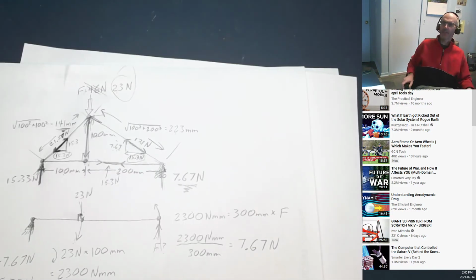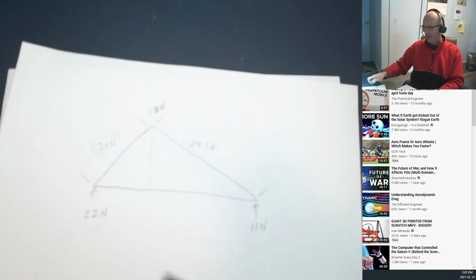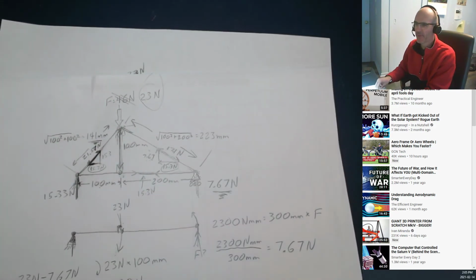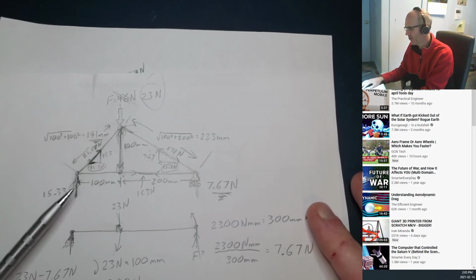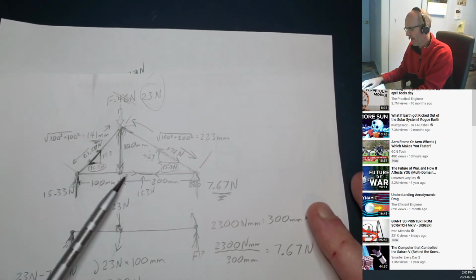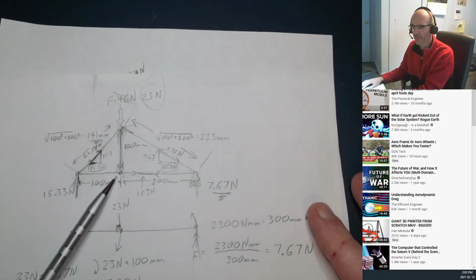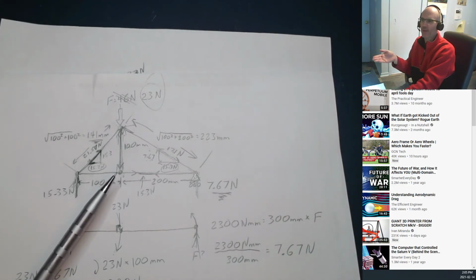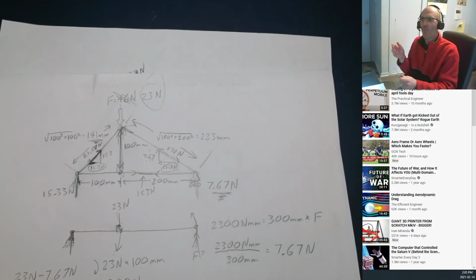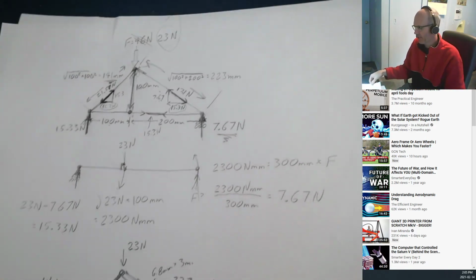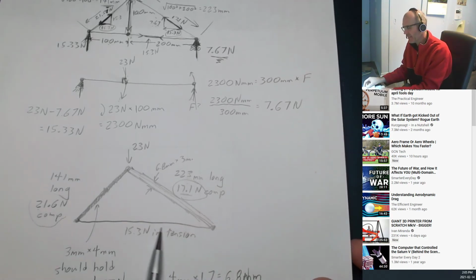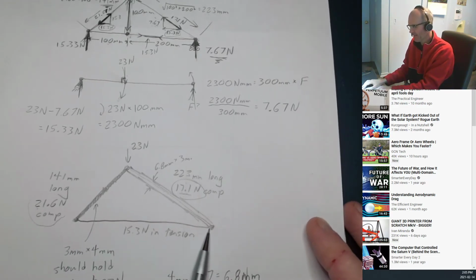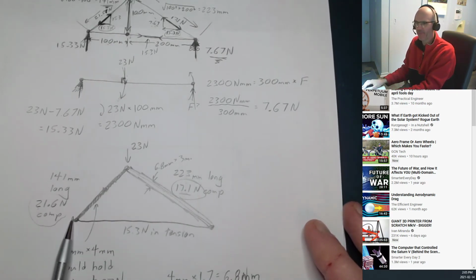Okay, so key concepts as we move forward. Well, truss analysis. We start with a truss. I give you some dimensions for the truss and a load. You can calculate the reaction forces and the compressive and tensile forces in each member. And hopefully you look at a truss and you quickly say, what's in compression, what's in tension. Why does it matter what's in compression and what's in tension? Well, it matters because the part that's in tension can be really thin and light. You can use a rope or a string, or in our case, a little 1 millimeter wide piece of MDF to support that.